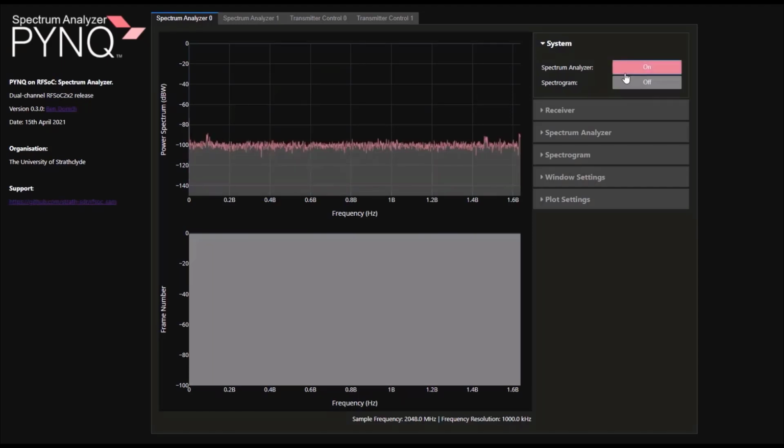As shown, we have switched on the spectrum analyzer. The input of the RFADC is connected to a bandpass filter that passes frequency components between 2340 MHz and 2530 MHz. A wideband amplifier and antenna is also used to improve signal power. Notice that we are currently tuned to Nyquist zone 1, which ranges between 0 and 2 GHz. The overall power spectrum is clear due to the bandpass filter at the input of our spectrum analyzer.